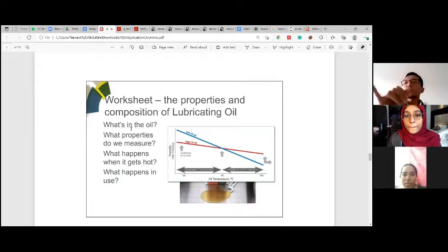Another thing that can cause the solidifying of the oil is actually contamination from when it's too hot or too cold. I guess when the engine is too hot and then it goes to the cold area, there's condensation, so the liquid mixed with the oil, then it changes the properties of the oil. That is one thing that I've read on the net as well.